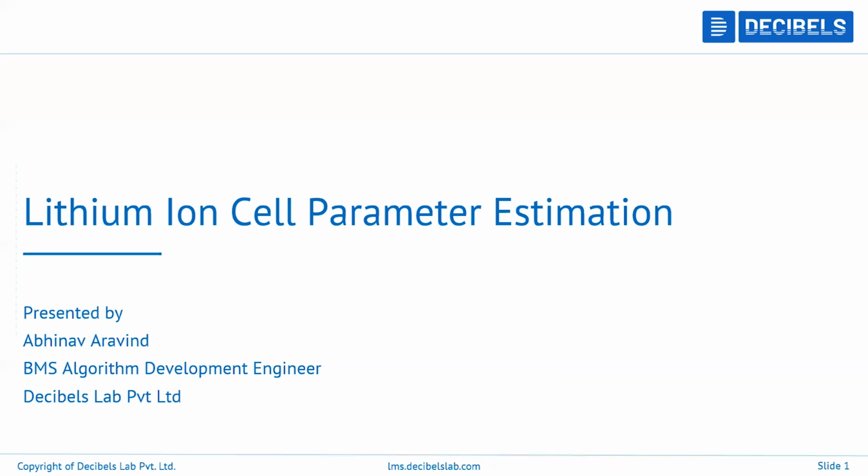My name is Abhinav Arvind. I'm a BMS Algorithm Development Engineer at Decibels Lab. I work on cell testing and also battery pack testing using various different equipment, cell cyclers and battery pack testing equipment. I analyze the test data and use it for developing algorithms for the battery management system, and also for developing certain other algorithms such as state of charge, state of health, state of energy, and all these things.